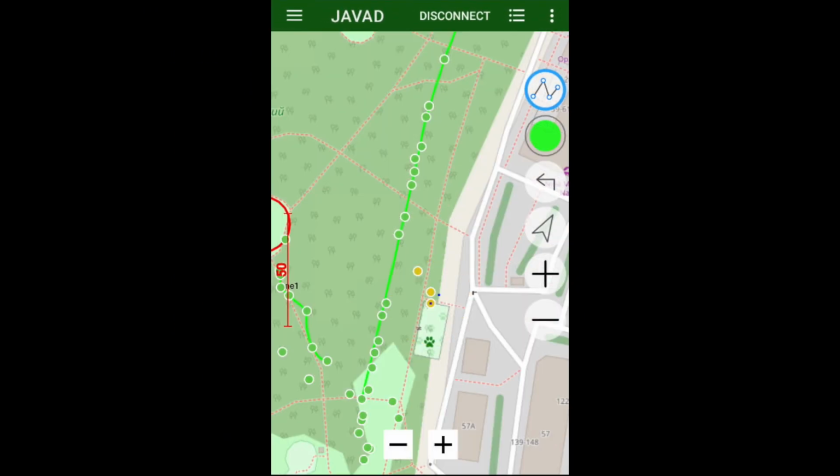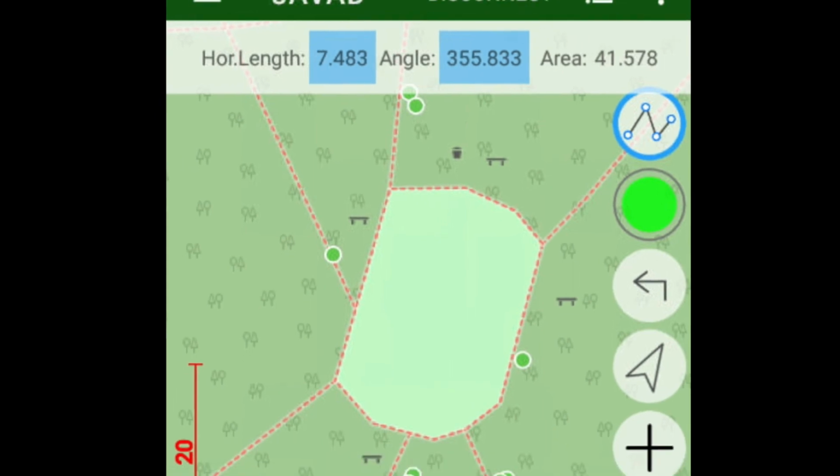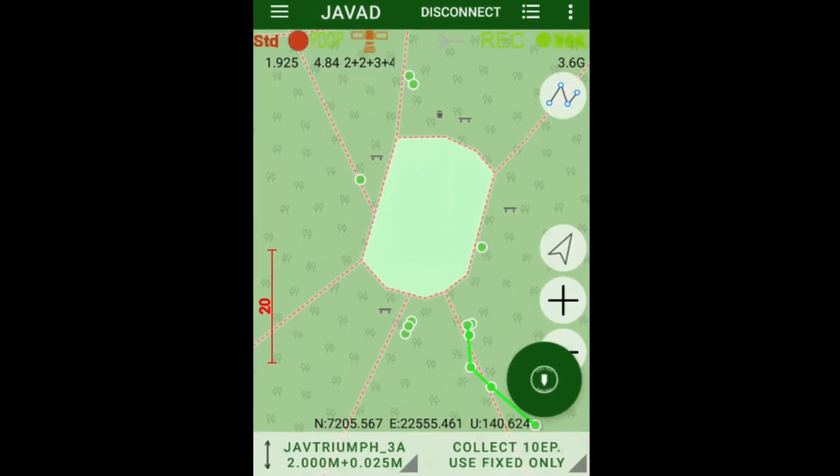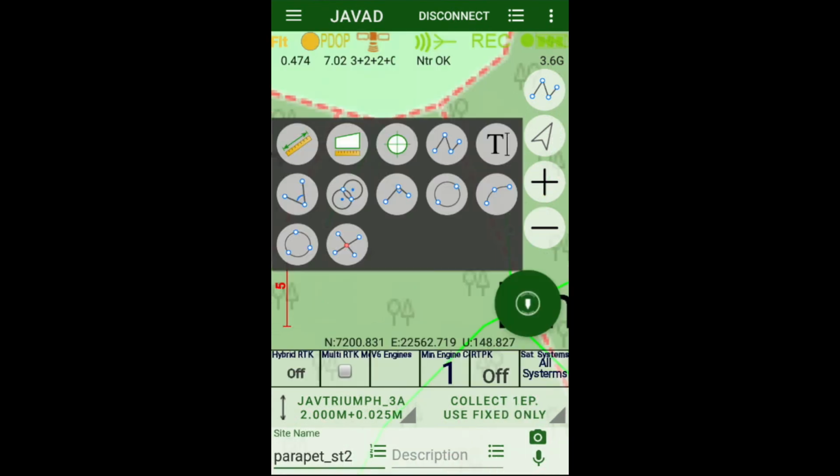And now you can draw polylines by clicking on the map. When a point or vertex is clicked, its coordinates will be used. A yellow circle around the point indicates that attaching to the point is used. To finish drawing, click the button again. The blue circle will disappear. Clicking the button again will open the toolbox to select a tool. All map tool items can be grouped into three parts: measuring tools, drawing tools, and computation tools.